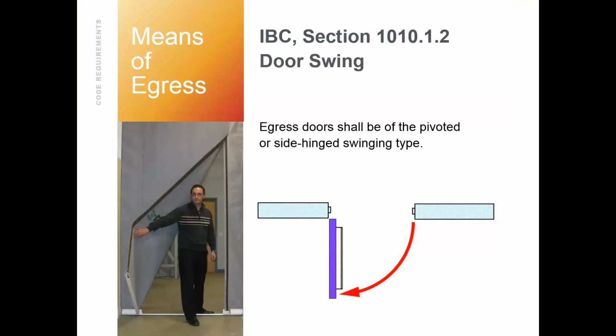So anyway, this technology is actually code complying under 1010.1.2, as we can see. It designates itself as a side hinge swing pivoted door by code. As you can see, there's this Velcro lining along the right side, the yellow, that seals the door. There's a push to exit. You push through that, the door goes open, but then there's this weighted bottom bar that slams the door shut. So there's like a closer affixed to the bottom bar. By code, it's a side hinge swing pivoted door with a closer and everything. It's just an alternative means of doing that.